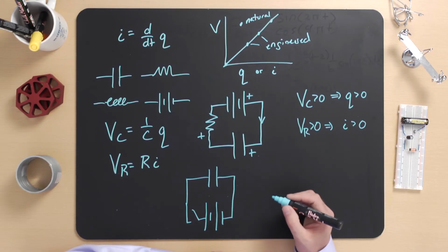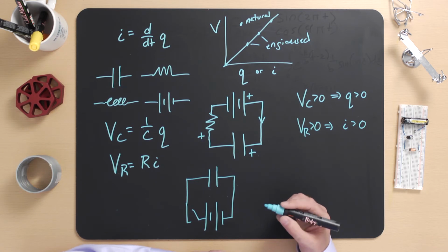However, the moment that the switch closes, this idealized system predicts that the capacitor will be instantly charged because its voltage V_C will be instantly equal to the battery voltage V_B. That probably seems unintuitive, but that's because real capacitors have what are called parasitic effects that include the non-ideal properties of resistors and inductors. Just like in mechanical systems, keeping in mind the difference between these idealized elements and the real physical elements they represent is a key skill you are developing in this class.